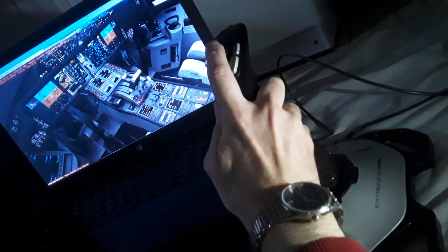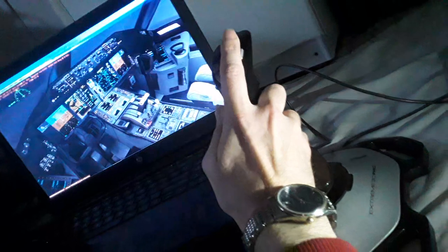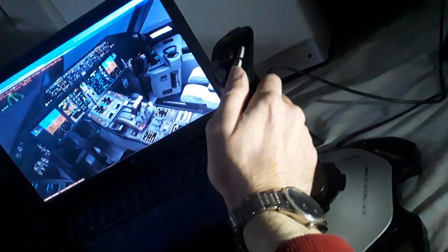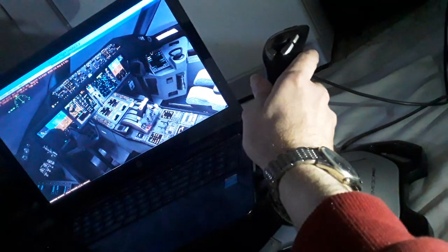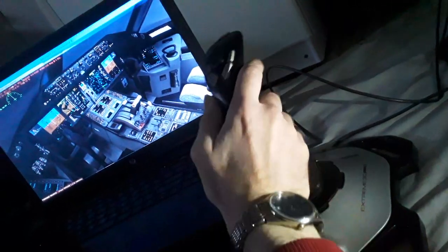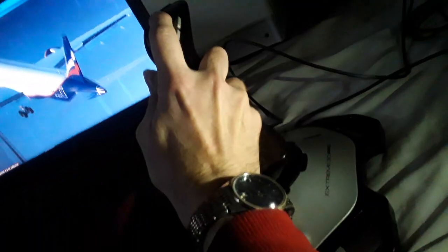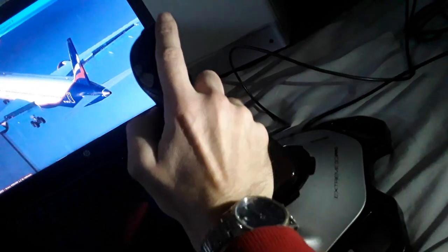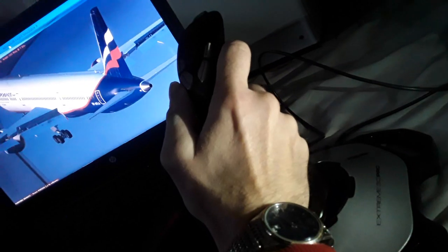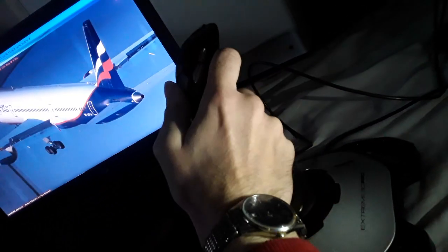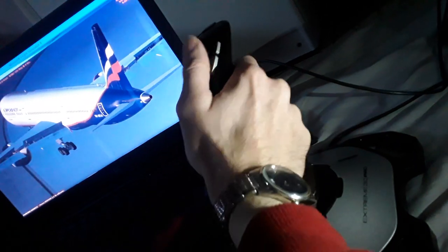They're not like in the Airbus, where you have the side stick priority. You can take either left or right side using the side stick priority button. Also the side stick deflection right now is proportional to the yoke deflection. Also the flight controls from outside. You can see the rudder again, rudder pedals, elevator for climb and descent. Over here ailerons and spoilers. So you climb like this, descend.